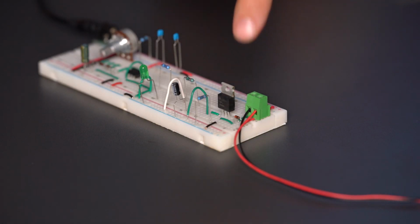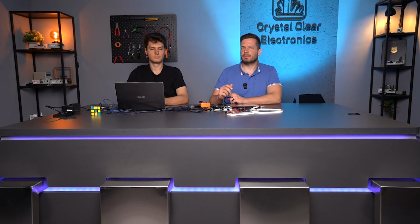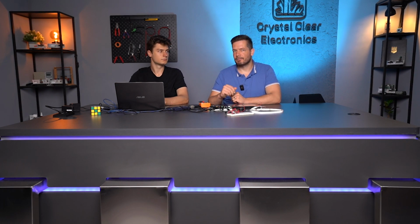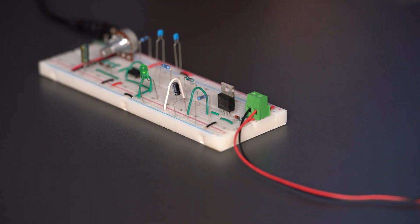Yes, understanding the function of the D3 diode is important when dealing with components that have inductance, such as coils, electric motors, and relays. It is recommended to place a protective diode next to these components to prevent voltage spikes when switching or interrupting the current flow. Currently, the FET Q1 is used for interrupting the current, or, if connected directly to the output of the 555 IC, the IC's internal drive circuit is utilized. By interrupting the current, we are trying to suddenly eliminate the magnetic energy of the coil in the motor, which is not possible due to the laws of physics.